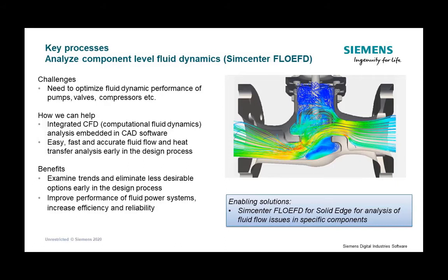Firstly, when looking at individual components of a fluid power system, such as pumps and valves, you can run a computational fluid dynamics analysis directly within your CAD software. SimCenter FloEFD for Solid Edge enables rapid setup of fluid flow analyses, and the analyses you run are associative to the CAD model. So if, for example, you make a change to the housing of a pump, you can run the analysis again immediately without the need to specify it again. Let's see a short demonstration of component-level CFD analysis.